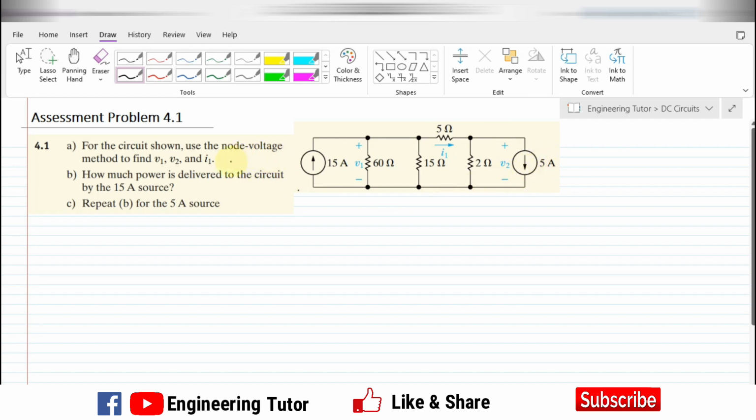So we have to apply the node voltage method. What is basically the node voltage method? In the node voltage method we identify the different nodes in a circuit, and then select one of those nodes as a reference node. After that we apply KCL over each node, and the analysis using KCL will eventually give us the required values.